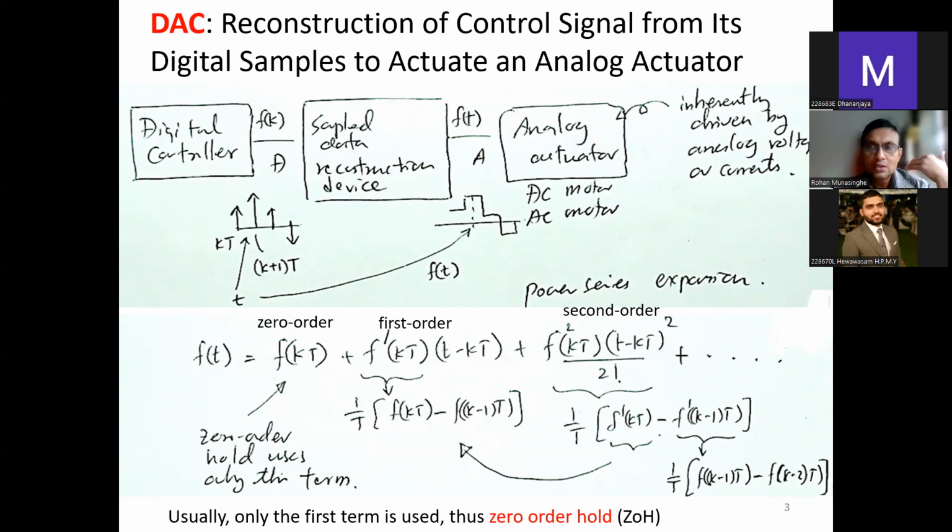So a digital to analog converter is basically converting the digital signal to an analog version. Okay. So it's like you have a set of samples like that, right? Like that. And you want to draw a line connecting these samples. And of course, you can understand there are so many ways to do that. If you are given a set of samples, and if I ask you, okay, what is the best fit for all of these samples, right? You can do various things. Okay. Smooth curve or flat top or ramp, right? A lot of mathematics on signal reconstruction, okay, using a set of samples.